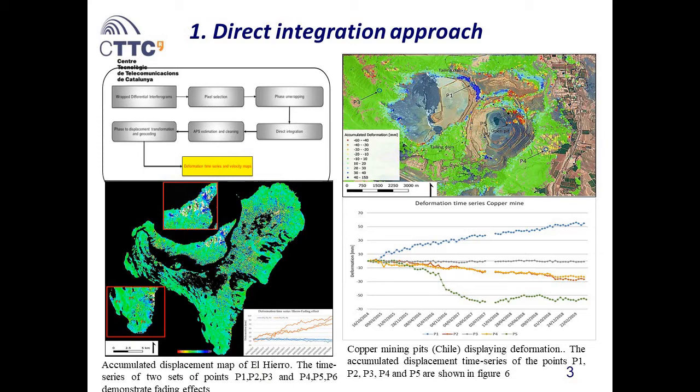When the direct integration was carried out in El Hierro, a systematic signal which shows no characteristics of noise was seen among the multi-looked interferograms, mimicking deformation signal patterns in some areas. This signal is named fading signals because the signal perishes with the increment in temporal baseline.